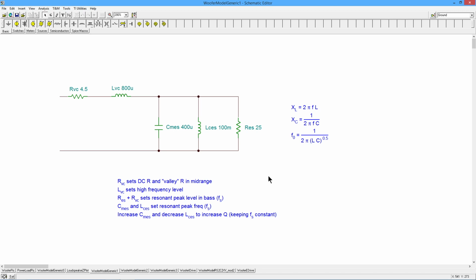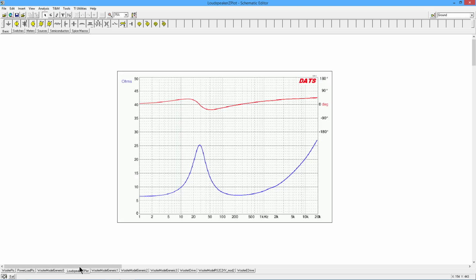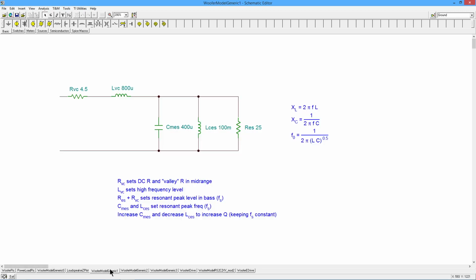So you look up on the Thiele small parameters, Fs, that's the frequency that we're looking for. So as an example, coming back to my plot, you can see here's 20 hertz, here's 30 hertz. We can see that just a little bit below 30 hertz, like maybe 28 hertz. So I have to manipulate these values to get that number through this equation, right?